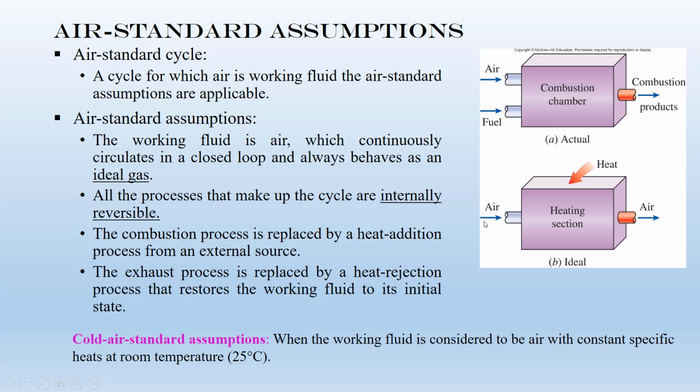The other thing is that, okay, if you have air, there is no combustion chamber. So what is the source for the heat in this combustion chamber? We assume that there is an external resource to just supply heat to this system. And then by having the information for the energy released by the air-fuel combustion reaction, we can actually get some idea about this heat. So this is some basic assumption for air standard cycle.